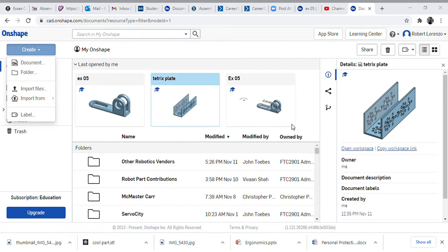So with that said, you should be able to quickly deduce that from the center to the outer edge of this arc is 25 millimeters. So this distance then is 90 plus 25 here, so we're up to 115, and we have to add 25 on this side as well. So this entire bottom piece is 140 millimeters.